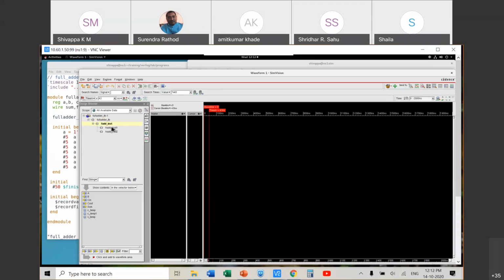TB. Under that, full adder inside the test bench full adder. This is the design top. Under that, half adder instance 1, half adder instance 2. Right? Now, if you look at here, this half adder instance, when you select, right, A B C S is what you are seeing. You can also filter out here, okay, hide unprobed and hide assertions, show transaction, this one, internal.